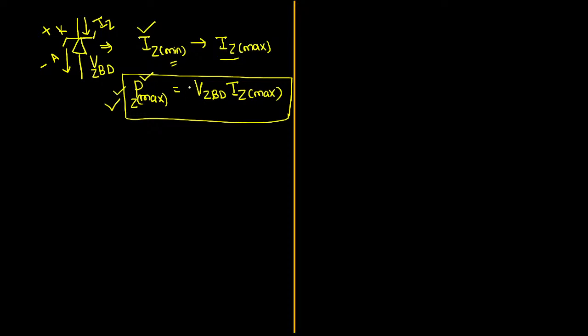So this is all about the Zener diode. Whenever a Zener diode is given, 98% of the time it will be operated in the reverse bias region only. In some cases it will also be operated in forward bias. In forward bias, you know what to do. You can treat your Zener diode as a normal PN junction diode. Just turn it on, keep 0.7 voltage across it, and proceed further. Anode is positive, cathode is negative. Current will go from anode to cathode in case of forward bias. That is all about the Zener diode.